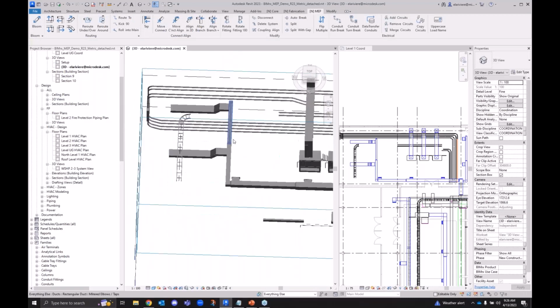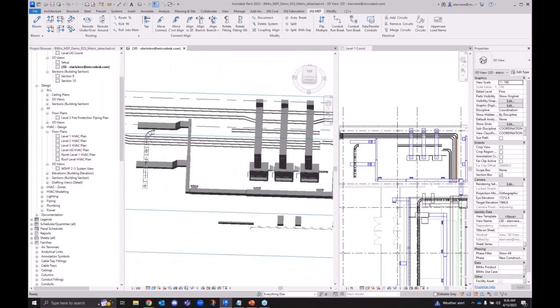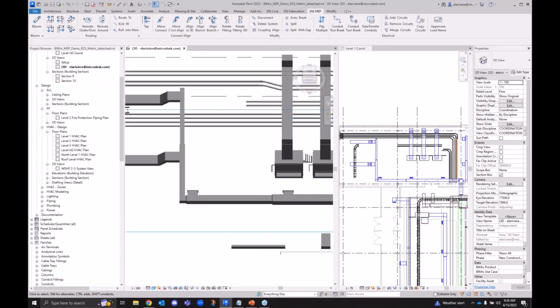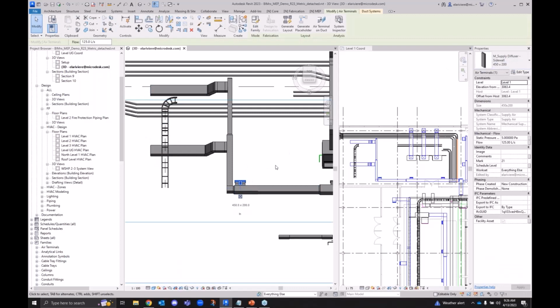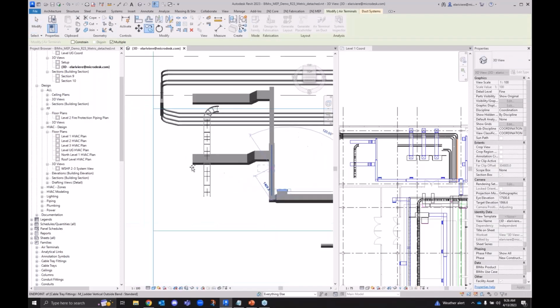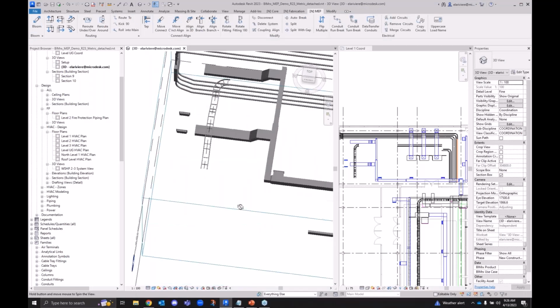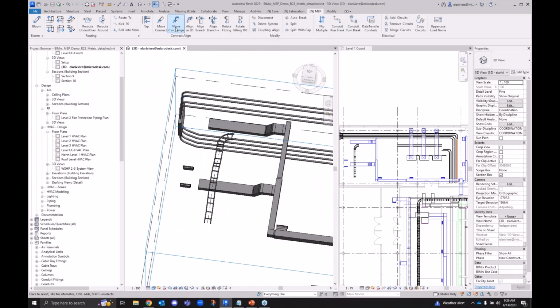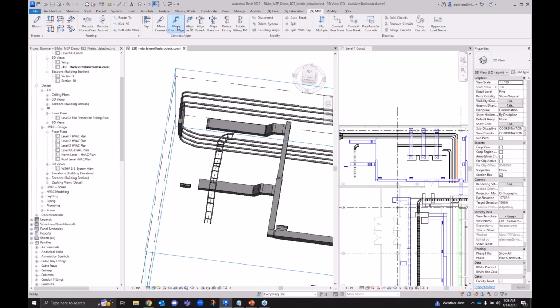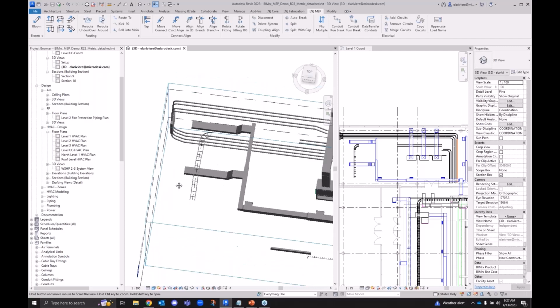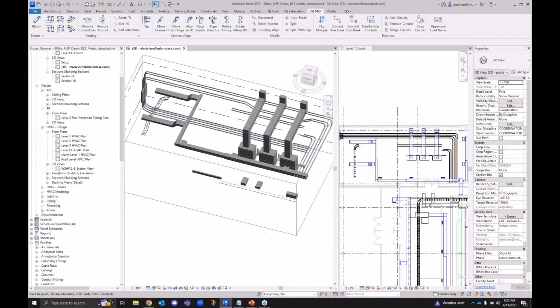All right. And let's do just a couple other quick ones over here, and then we'll move into a new area. If you catch over here, I don't actually have any air terminals on the end of those ducts. Just want to show you a fun, nifty little thing we can do here. Right. So I've got some diffusers that have been kicking around. I'm going to make a copy of both of those and just get them kind of close. So if you remember before, we've got a really nice move connect align. So anytime you're working with rotated portions of the building or you're copying elements around, don't do all those extra steps, rotating or prepping them ahead of time. Let Naviate take care of that for you. As long as you know the design you want, we're going to be able to help you make it.